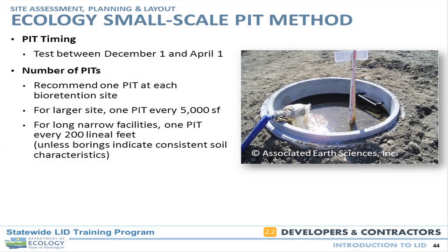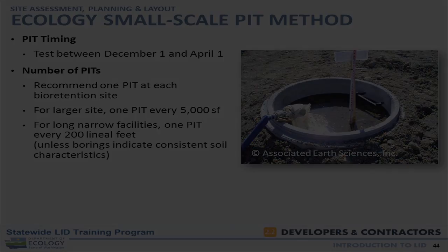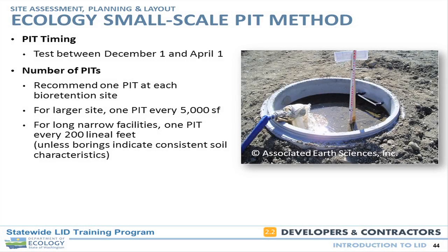A pit test, a pilot-scale infiltration test, is really what's needed to get a design infiltration rate. It's not considered sufficient anymore to go with a grain size analysis approach or even a double ring infiltrometer or some kind of small-scale test. The findings over many years are that those are notoriously inaccurate, and that the only way to really get a true infiltration rate is to use the pit test method.